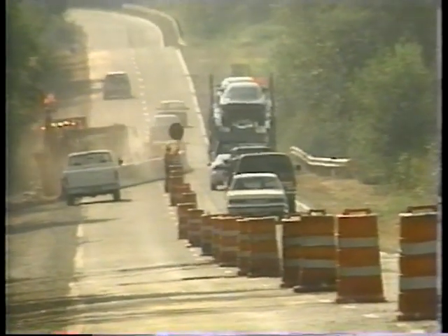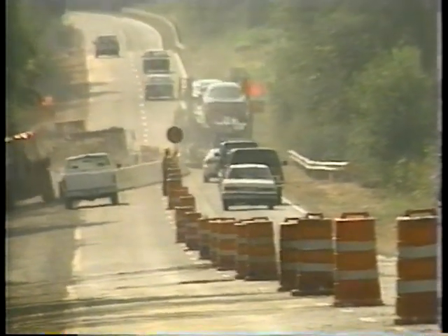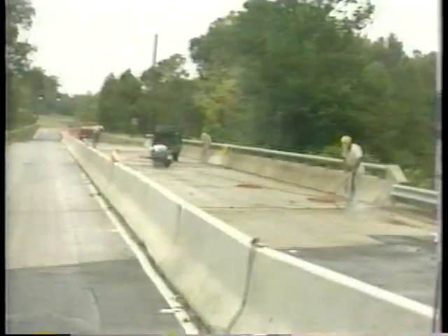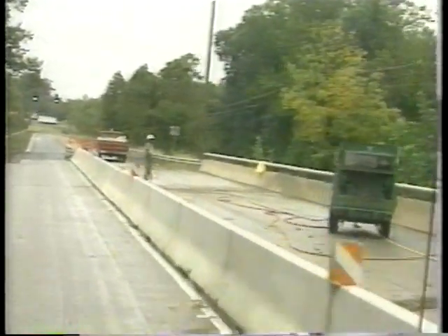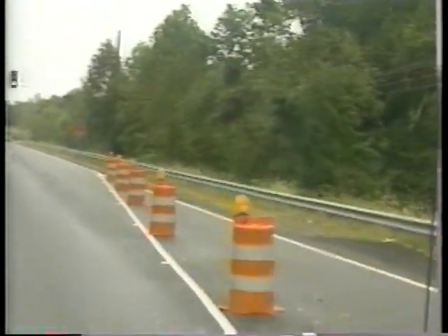Next, install pavement markings, signing, and channelization devices such as traffic cones or barricades. Remember, they must be effective during nighttime and bad weather. If special conditions mean none of these devices will be effective, then use flaggers. A final principle calls for routine inspections. Drive-through inspections can check for safe travel paths and visibility under all conditions.